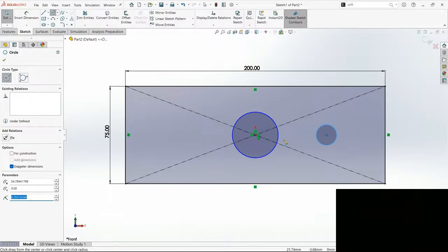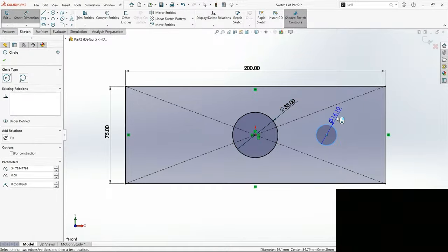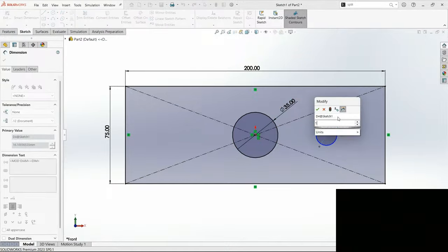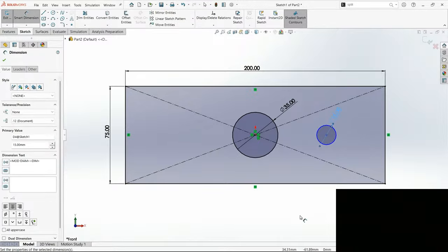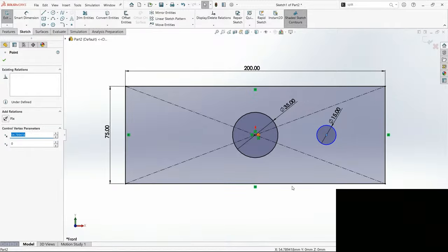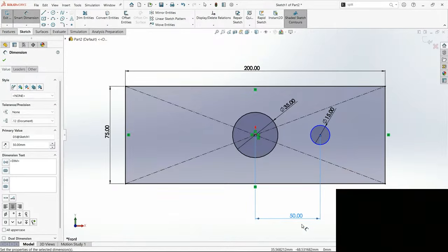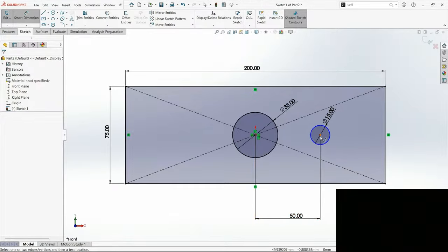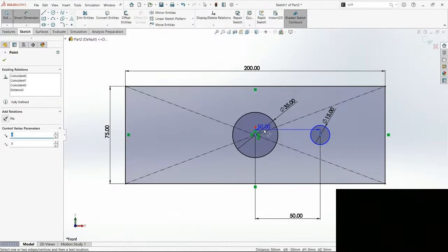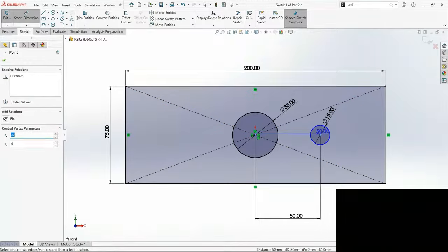If you want to define the dimensions for this, I'll assign 35 here, and let's consider this as 16, or 15 is fine. You can even define the dimensions to make it standard. Let's say you want to do this analysis again and cross verify everything, you will need the dimensions, right? So consider these as a reference for us. I'll just make this one vertical.